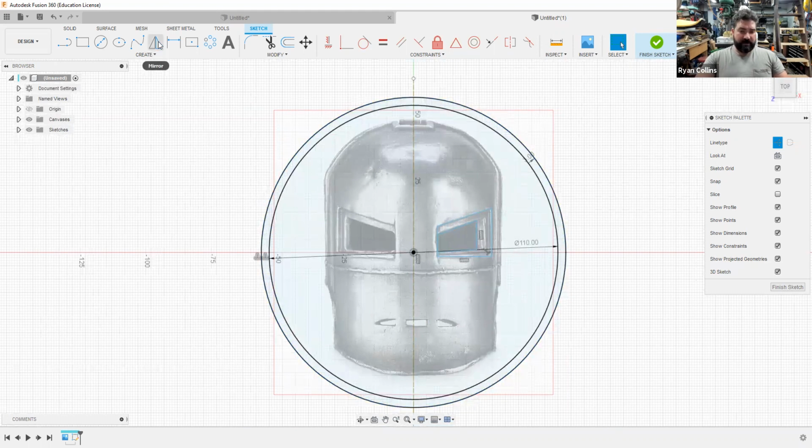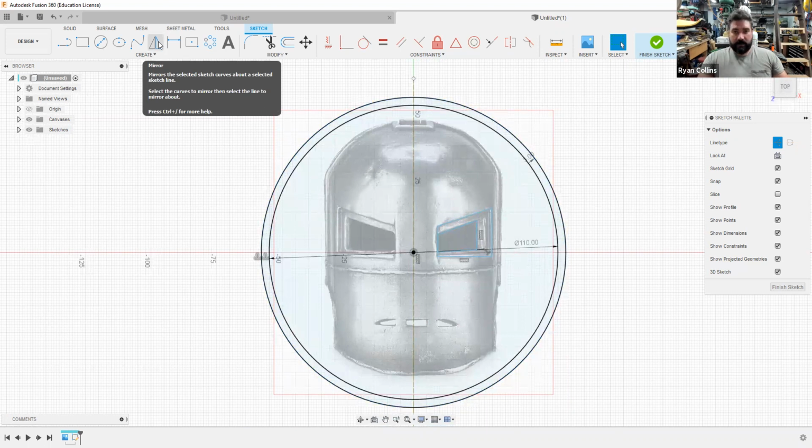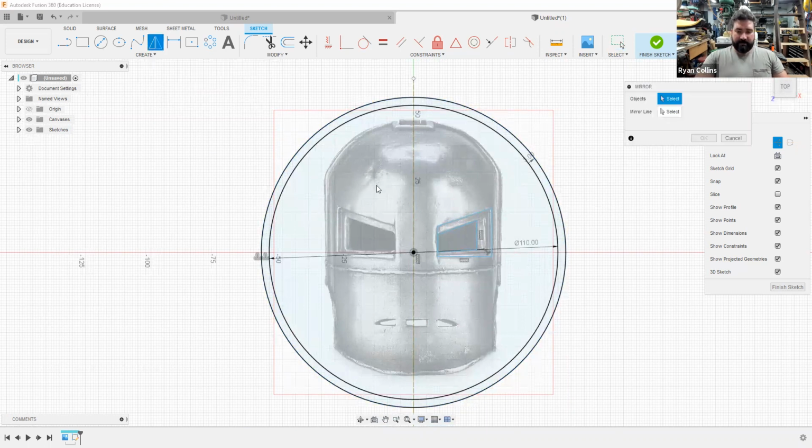The one other tool that is shown here at the top by default is mirror. It makes an opposite thing. So select that mirror tool. I want both of these eye socket things that I was working on. Well, I can double click them, and that'll select the whole enclosed line, or I can use a selection box, just like on a lot of standard things. Click and hold from the left and drag right, and it will select anything that is completely inside of that box. See, it did not select that construction line, but it did select the two eye socket lines there.